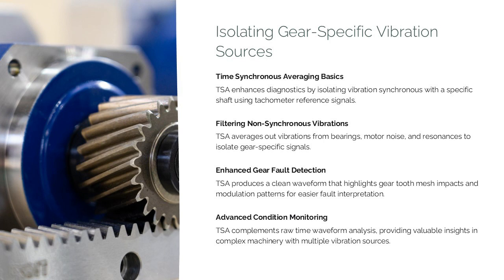Although TSA requires careful setup and longer acquisition times, the diagnostic benefits are substantial. The resulting waveform makes subtle gear faults more visible and easier to interpret, particularly in complex machinery where multiple vibration sources are present. TSA is therefore a valuable complement to raw time waveform analysis in advanced gearbox condition monitoring programs.